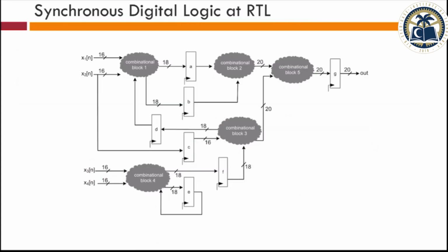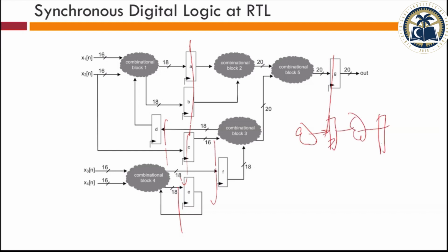So that is the target which is given to you, that you are planning to run this device at a certain clock. We usually call this F clock. Okay, so these are the two major design parameters that you have: at what rate you have to process your data and at what clock you are targeting to run your circuit. So your design would always look like this, where you have registers or memory, storage, and because it is a synchronous circuit, you got to break all the logic as an architect into cloud and register, cloud and register, cloud and register.